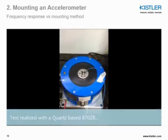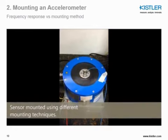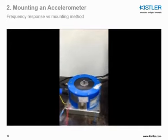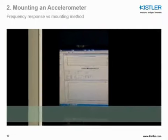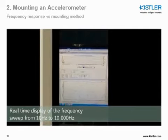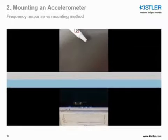We are using an 8702B500 quartz-based sensor that is being mounted in different ways on the shaker. We then run a frequency sweep from 10 Hz to 10,000 Hz, and we will look at the sensitivity deviation and the frequency deviation.